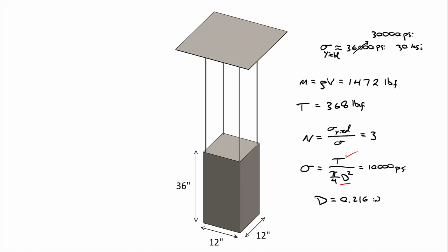That's a great point. In the real world, you're going to pick something from a standard size. So since you can only buy increments like 1/16 of an inch, you probably round up to the next standard size that's at least a little bit bigger than 0.216 inches. That might be something like a 1/4 inch rod, which is 0.25 inches, or even a bit larger just to stay on the safe side. That way you have a nice safety margin and a standard size that you can actually purchase. Oh, I think we already got enough safety margin.